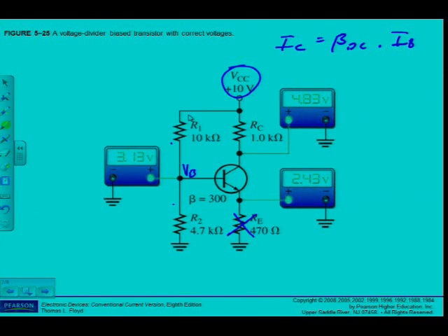And so if I calculate VB is equal to 3,2 volts, what is VE going to be equal to? What is VE going to be equal to? If I look in the circuit, I've calculated that and I've actually measured that. Now 3,13. So I can see there's a small difference because of the assumptions that I have made. Alright? So what is the difference between VB and VE? We assume again approximately 0,7 volts, which should give me a value of 2,5 volts. I can see I should actually then measure 2,43.